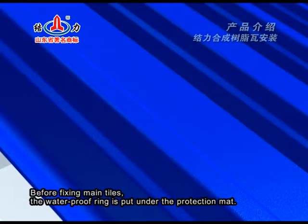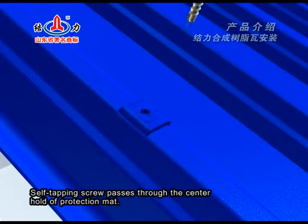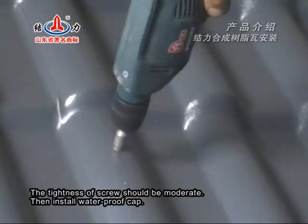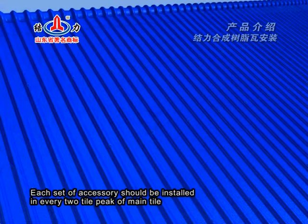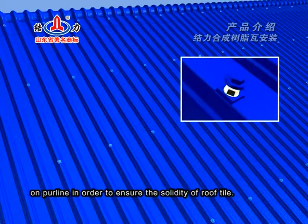Before fixing main tiles, the waterproof ring is put under the protection mat. The arc side of the protection mat should be on bottom side. Self-tapping screw passes through the center hole of the protection mat. The drill should be vertical with tile surface. The tightness of screw should be moderate. Then install waterproof cap. Each set of accessories should be installed in every two tile peaks of main tile on purlin in order to ensure the solidity of roof tile.